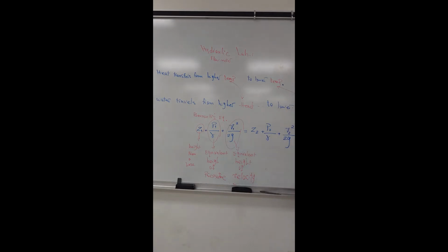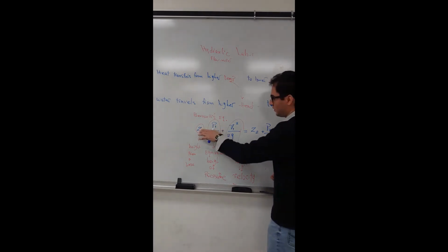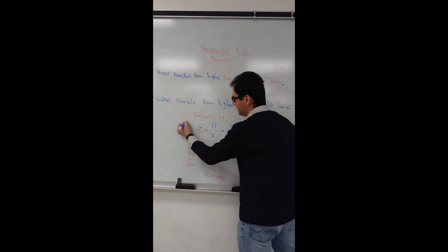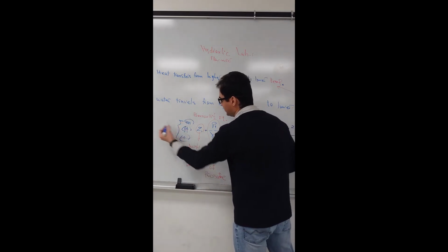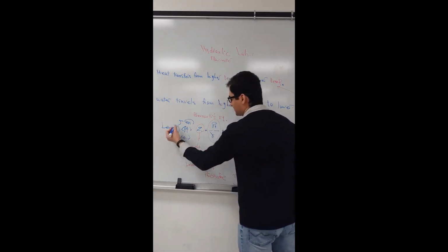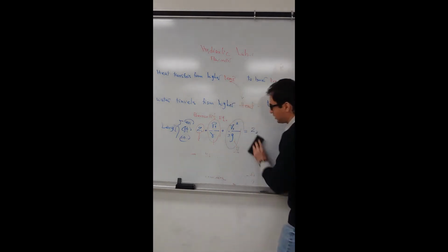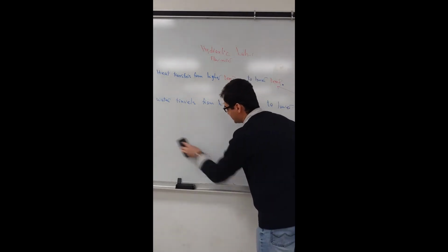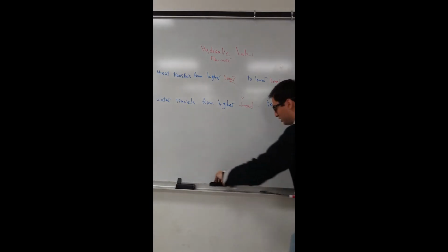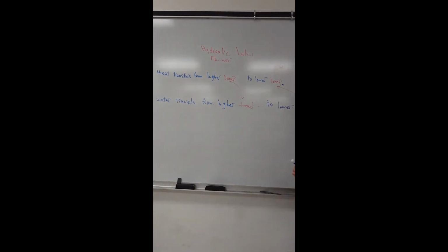The reason they are called equivalent height of pressure or equivalent height of velocity is because the unit of all these three should be in meter, feet, or inch, whatever it is, in terms of a length, either in SI unit or British unit. So let's take a closer look at what's happening in Bernoulli's equation in terms of dimensional analysis, to see how to reach the same unit for all three terms.